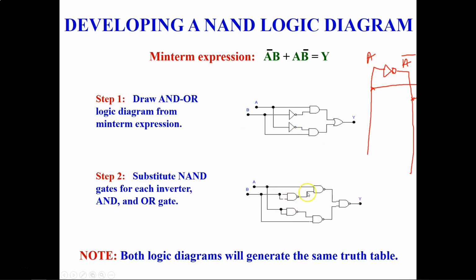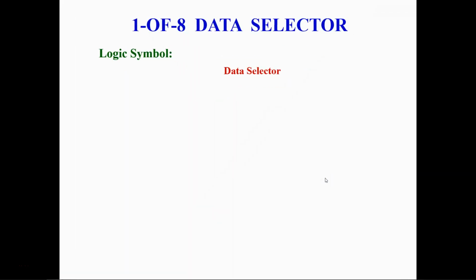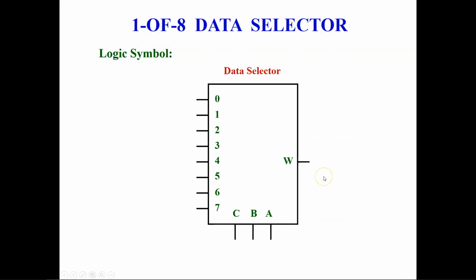You have to feed in all the inputs. So for example, A is going here, and you have B going in here, and then the other input is going in here, and same here, A is going in here. Okay, and you have to test out what output you are getting out of these NAND gates, and how they are the same as above.